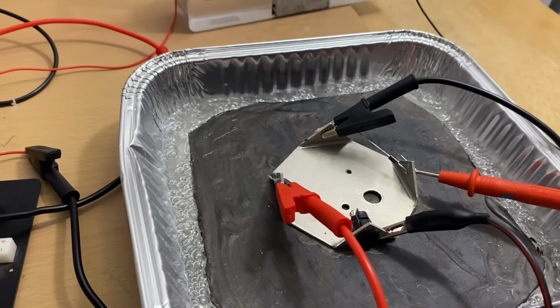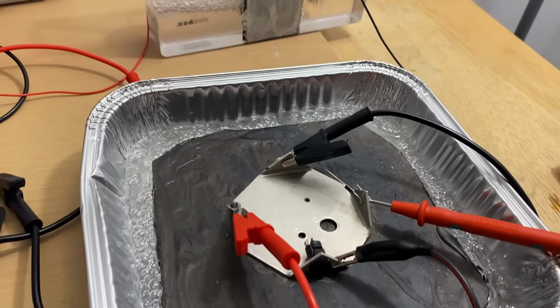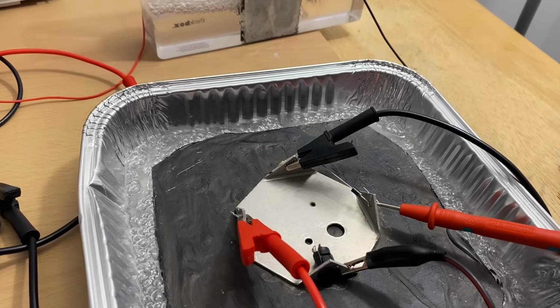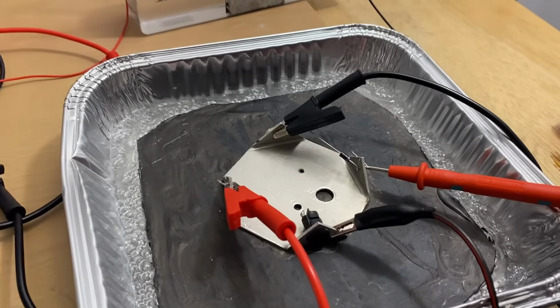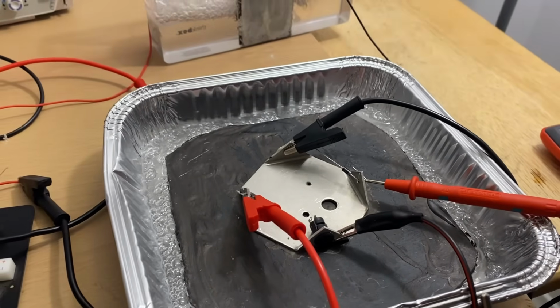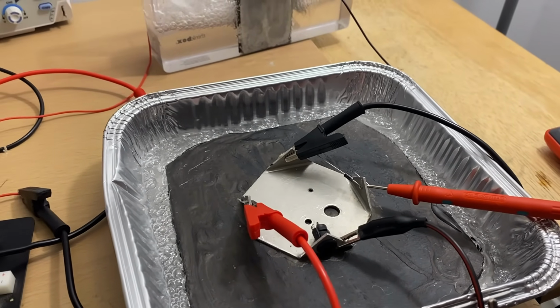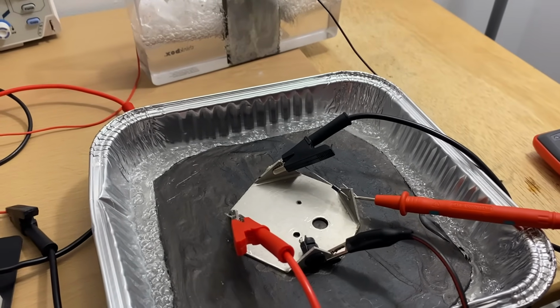And what's going to happen is when we turn this on, because of the non-ideal cell, it's going to want to flip polarity, like acting like a really bad cell that can't even provide enough current to make it through the loop. Then it gets reverse biased, right? A normal cell that's really bad would just act as a load instead of a contributor and suck up, basically a low impedance load.